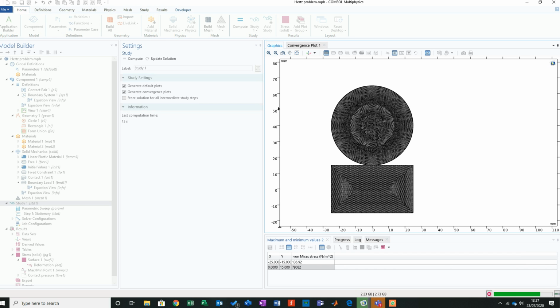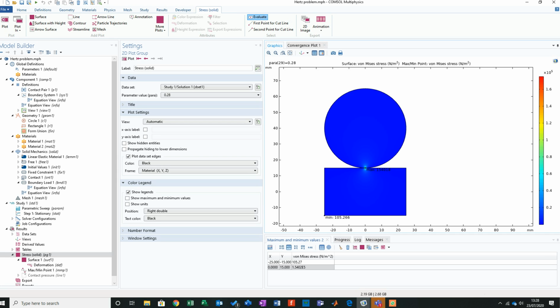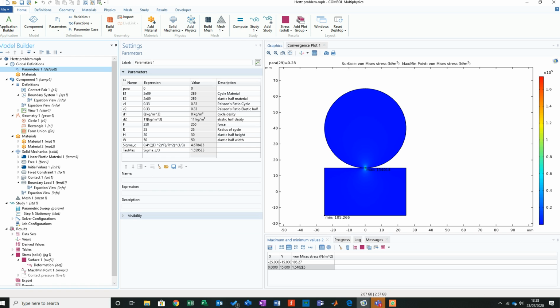So I'm running through again on extremely fine. I still think that this is going to give us a result that's still out, but it will give us that indication if we are on the right boat. Because if you think about it, between them 2 points where our surface area interfaces, oh look at that, what we get is something a little bit more accurate. So let's see where we are. Going to this, we're at 1.54 to the power of 5. According to our theoretical solution, we're 1.56559 to the power of 5.